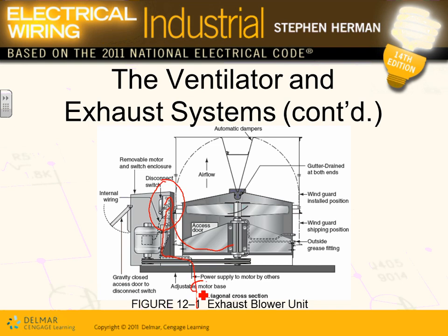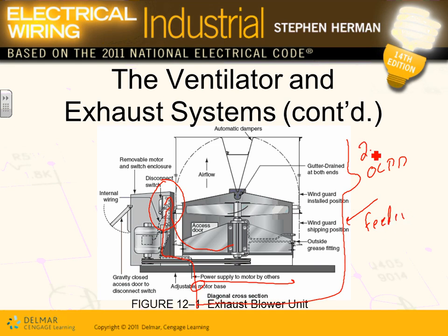So Adam, my job and yours is to take this and give it a circuit breaker, an overcurrent protection device, as well as provide a feeder. This one, guys, is typically 2.5 times full load current, which you guys did. And this feeder is 1.25 times full load current. Done. That's how we size the feeder and overcurrent protection device. The motor, you guys have, I tested you for that one on the motors.